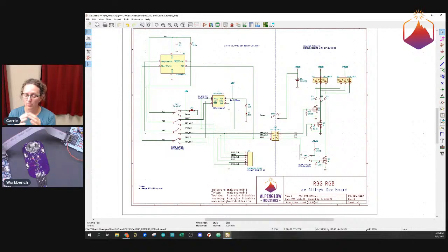There are fewer, and with the electronics parts shortage going on, if I got into a place where the dual transistor package in the configuration I needed in the size that I needed could easily not be available. Whereas a typical single transistor in a single package, I'm using the same size package, essentially. It just has 3 pins instead of 6. And that is going to be available by many, many different manufacturers, and it will be no problem to substitute a different one in. So that's why I made that decision, purely from a sourcing perspective.